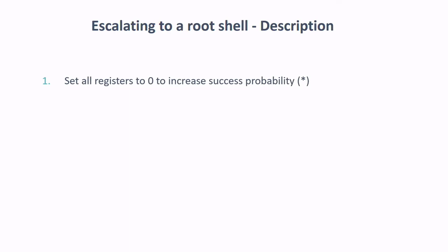Keep in mind that when you actually call a function, there is always a result returned to the caller, like yes, true, or no, false. This is usually represented with some binary value in the assembly, in the call. So we thought, perhaps if we set all the registers to this good value, this value might be returned to the caller by our glitch. We don't know how. So it would not be possible for us to say, hey, in this code we were able to. But we are able to say that statistically we have been able to affect that.